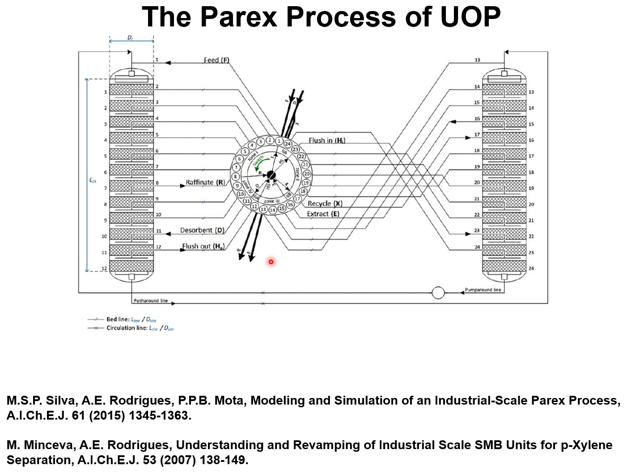The beds are stationary, and the essence of countercurrent liquid adsorbent contacting is achieved by switching of the valves. So the movement of the bed is simulated, and that is the reason it is called SMB technology, or simulated moving bed. The beds are stationary.